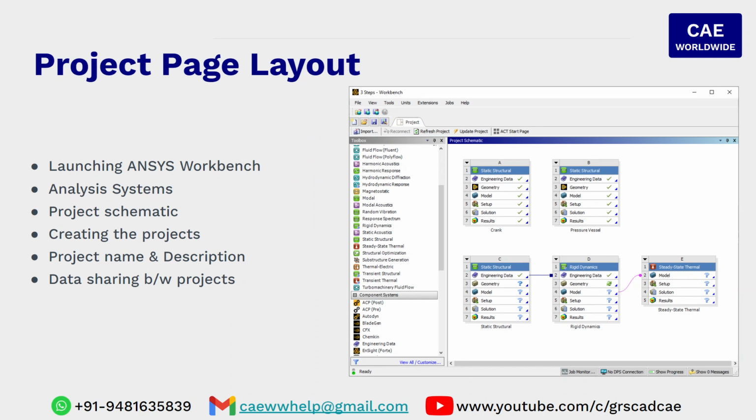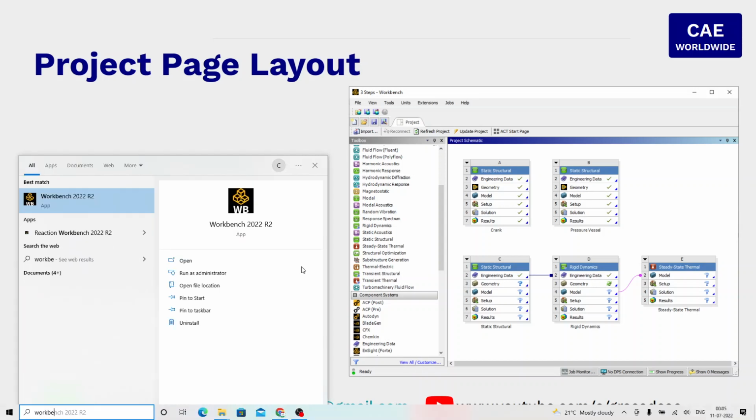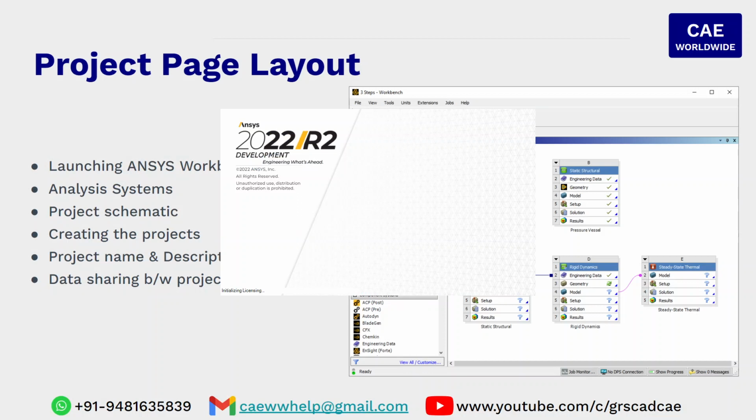First, to begin with, I will take you through how we can get started with the Ansys Workbench. We are going to start and type here Workbench. If you haven't installed Ansys Workbench on your machine, then please see my previous video on how to download and install Ansys Workbench, where I have clearly defined the system requirements and limitations of the student version of Ansys, and also what is included in this package. Click on Ansys Workbench 2022 R2.